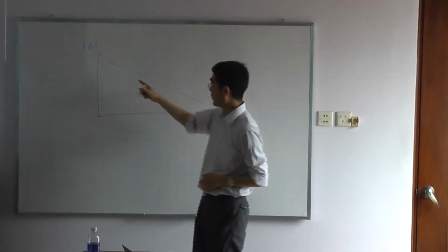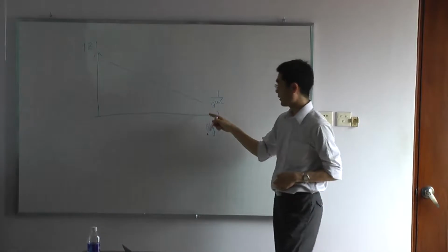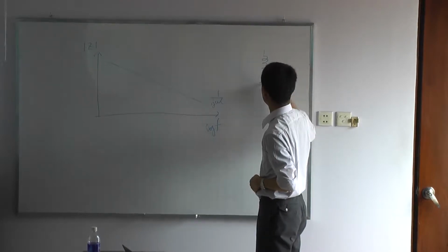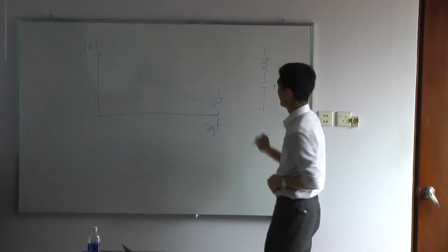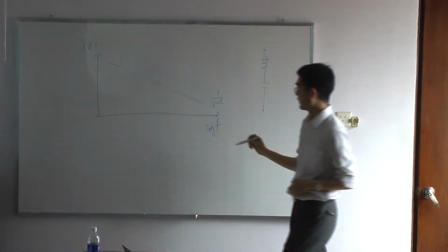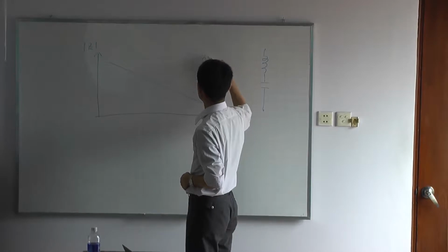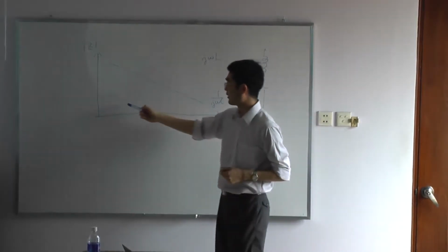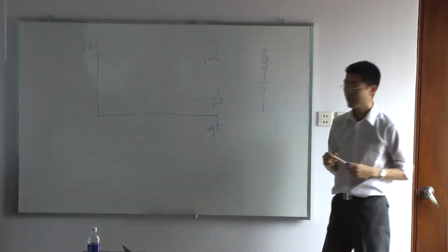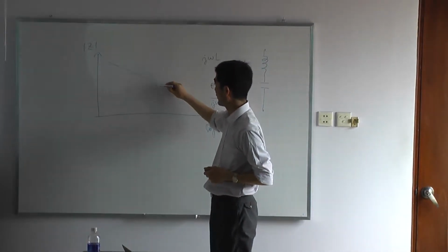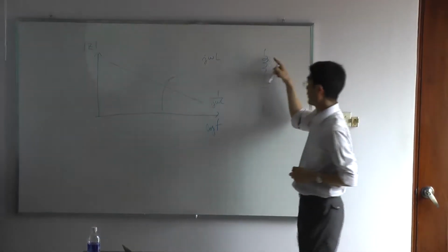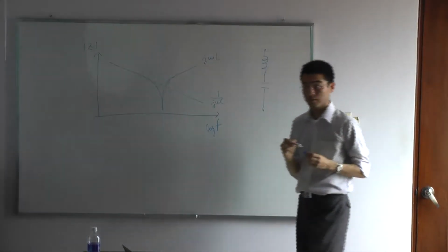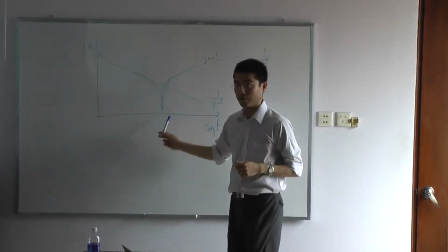the impedance becoming smaller as frequency goes higher for the capacitor. Let's say we have this kind of circuit. And in that sense, the impedance of the inductor is getting higher as frequency goes higher. At this point, we have a resonance frequency, and the total impedance of these two elements comes out like this. We call it the resonance frequency.